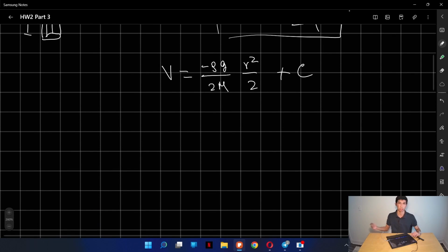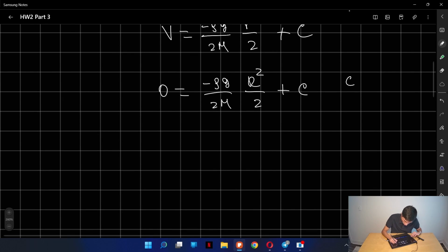And in order to find the constant, plus C, we know that the velocity at the wall is going to be equal to 0, right? So we can find that using this equation. When r is equal to the capital R, the velocity should be equal to 0. So our C is going to be equal to rho g R squared over 4 mu, right? Viscosity.